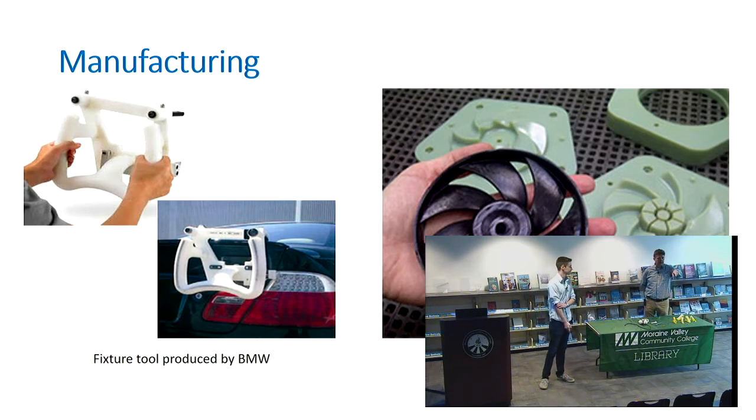The other part that's going around, the small blue clip, was injection molded from plastic 3D printed molds. So the molds can be done in plastic, or they can actually be done in metal now. Both of those parts, the large shape, that's aluminum, and that was cast with aluminum, but from 3D printed molds.